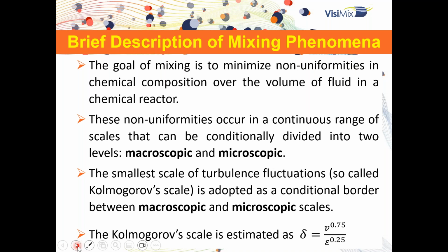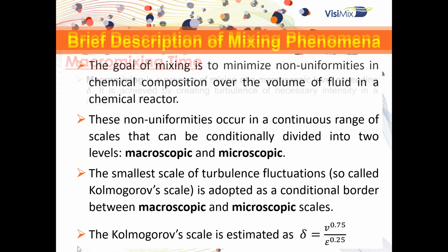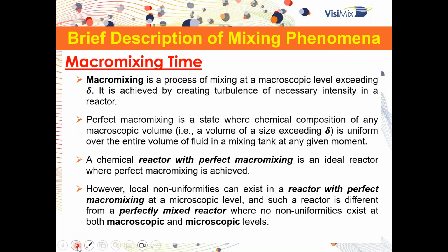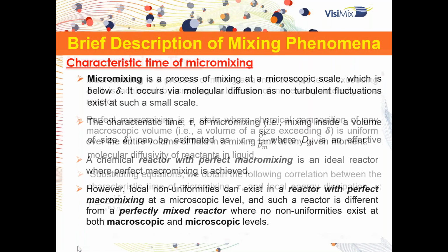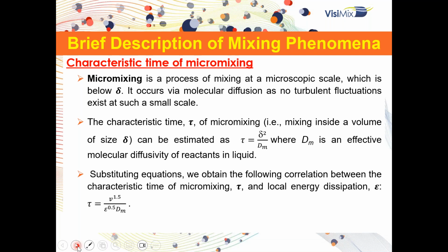The main activity is to include the local diffusivity by Kolmogorov estimated size and the eddy size, and by definition the influence of the micro mixing in the tank, because inside every eddy that's moving and generating the macro homogeneity, we will have internal diffusivity. What happens with the internal diffusivity in the eddy zone.